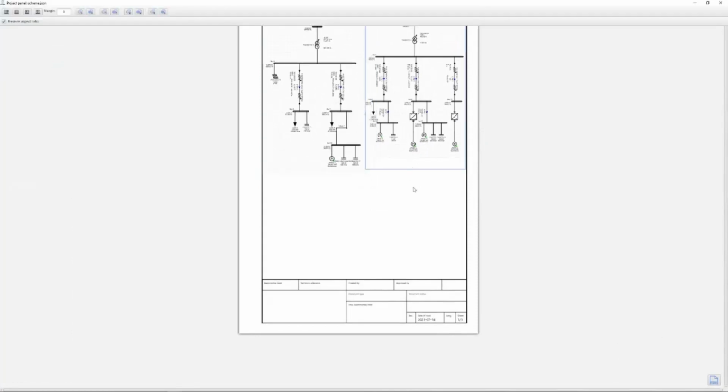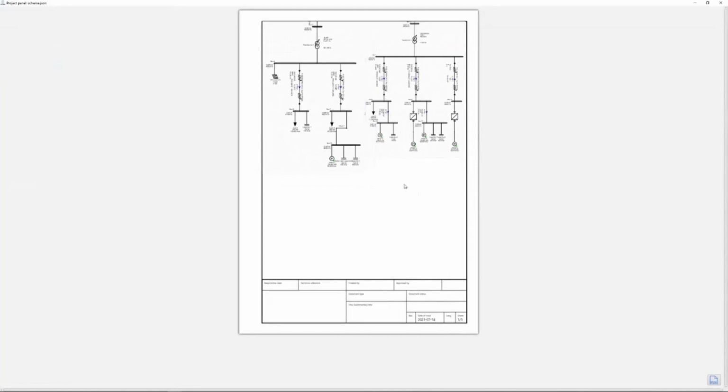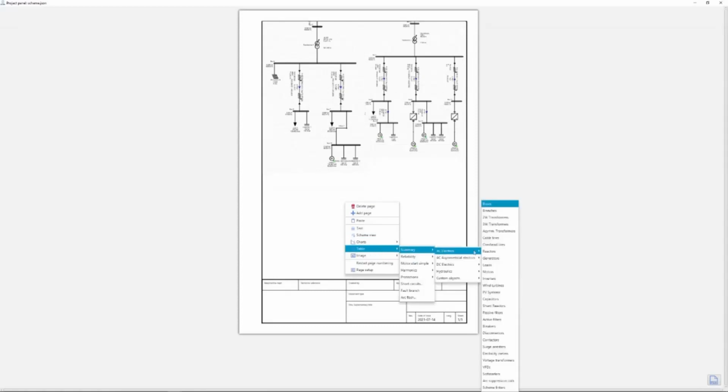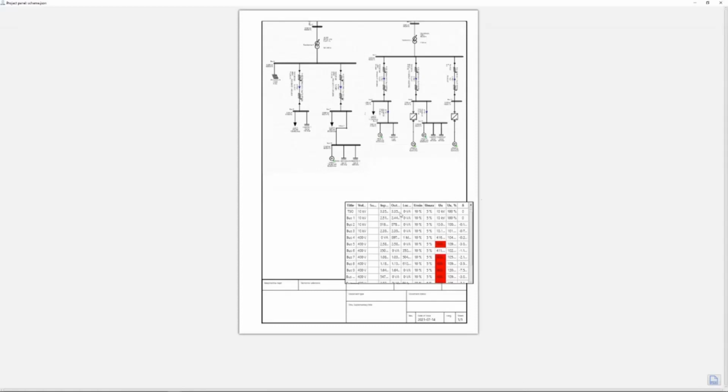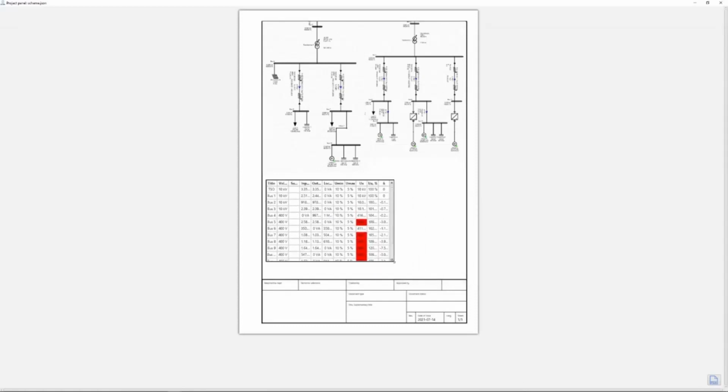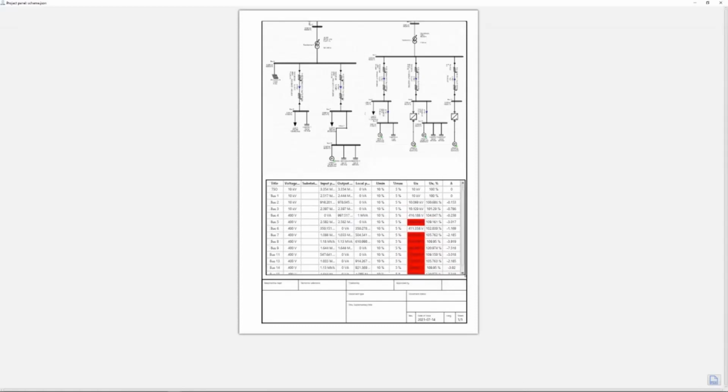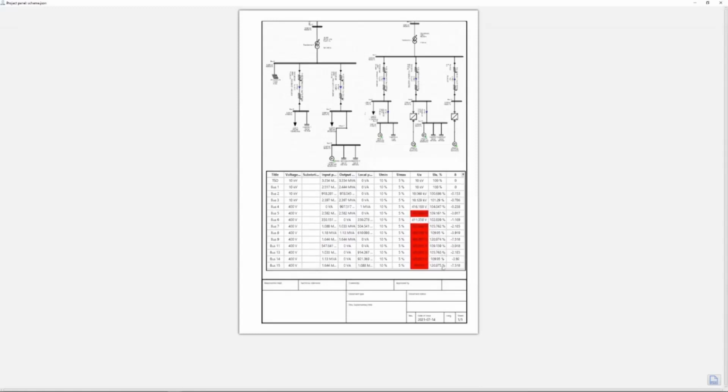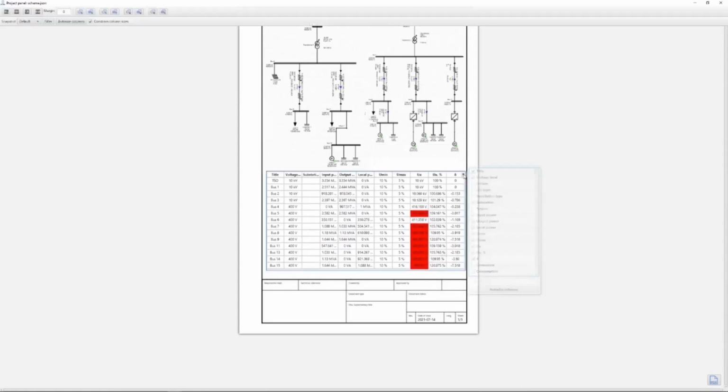And now, when you have added your photos, you can right-click on the project panel, and there is a lot of things you can add, such as text, scheme view, charts, tables, images. So now I'm gonna paste a table in that is from summary, AC electric, and the buses that checks the voltages. But now we're seeing the results when all the capacitor batteries are turned on. That is a thing we do not want.